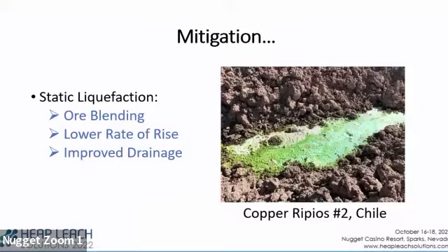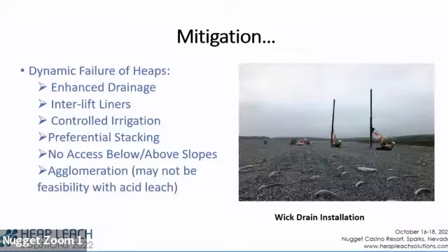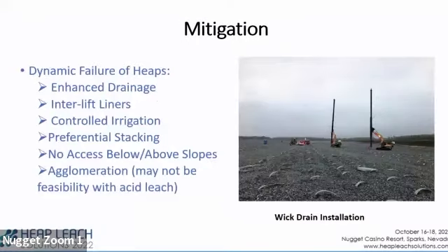Improved drainage is always the answer to kind of every bad thing in geotechnical engineering. And wick drains are a fantastic tool. Freeport uses these routinely as a matter of policy. There are 2 heap leach projects in Chile operating with regular wick drain augmentation of their drainage. They're not free, but they're not horribly expensive, and the cost is absolutely predictable, and the benefit is absolutely predictable. So if it works, it's the thing you want to use.